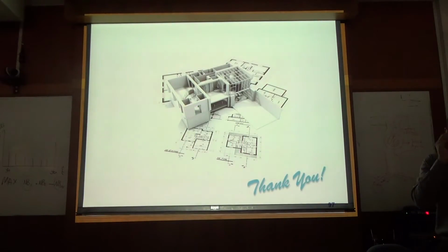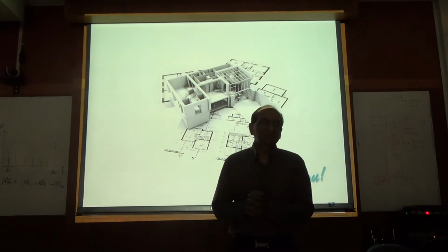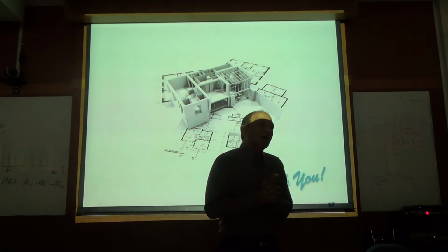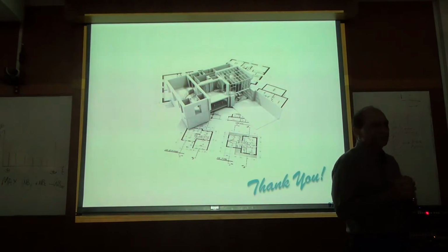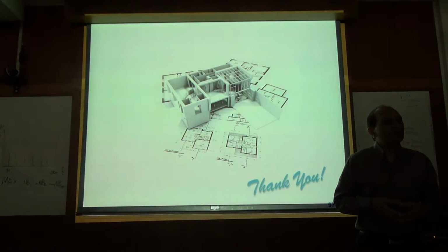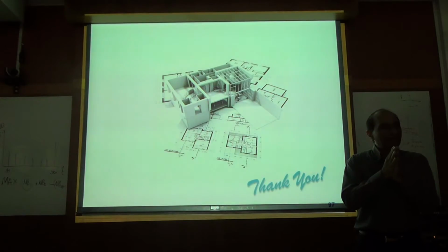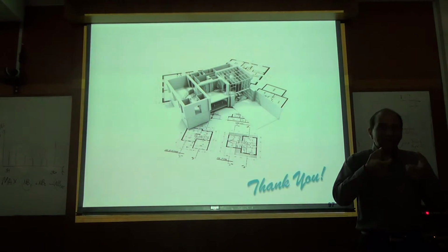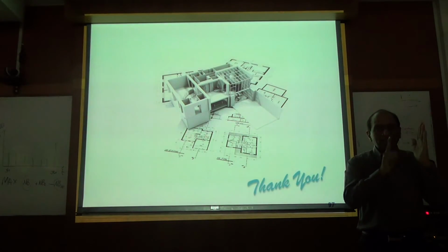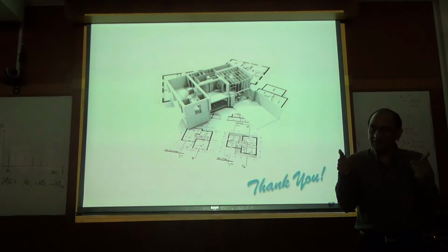All right, thank you. So this concludes the discussion before I open the program. Any questions? One thing that I did not tell you yet, hinge length. We talked about moment curvature. We did not talk about moment rotation. In one of the previous slides, you need to multiply the curvature by a certain length to get the rotation. That means curvature is at one section, but if you add up all the curvatures over a certain length, it will become rotation. And that length is called hinge length.